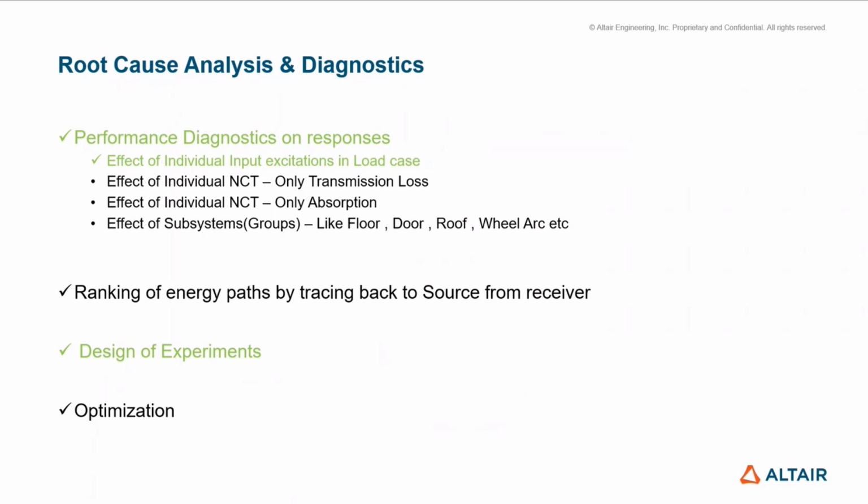diagnostics on response, like the effect of each individual excitation in a load case. As the number of excitations in each load case is pretty high in a general automotive use case, you want to identify from which particular excitation or source the most contributions are coming into the cavity. And the second thing is the effect of individual NCTs, in terms of whether the transmission loss is having the major effect or absorption is having the major effect, or at which particular region the NCT is not behaving properly. So we want to achieve those contribution analyses in terms of both transmission loss and absorption.